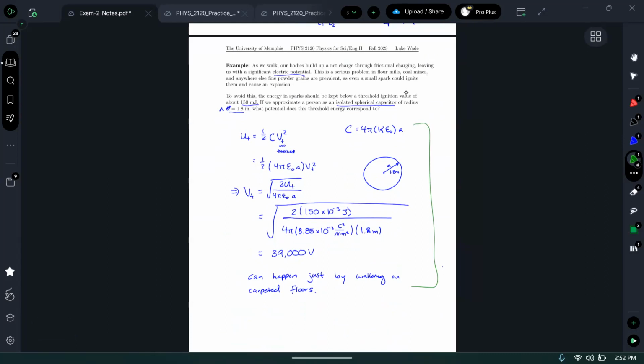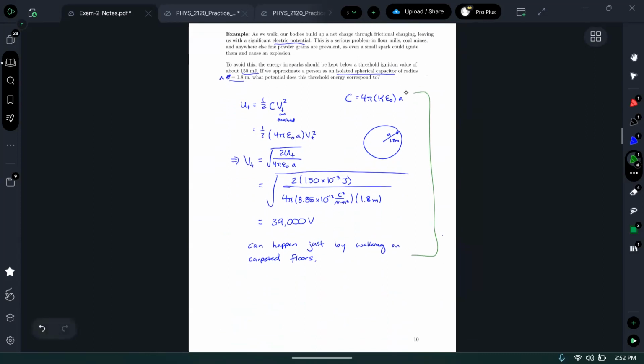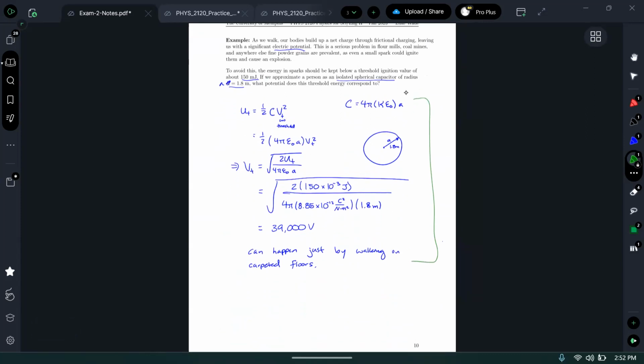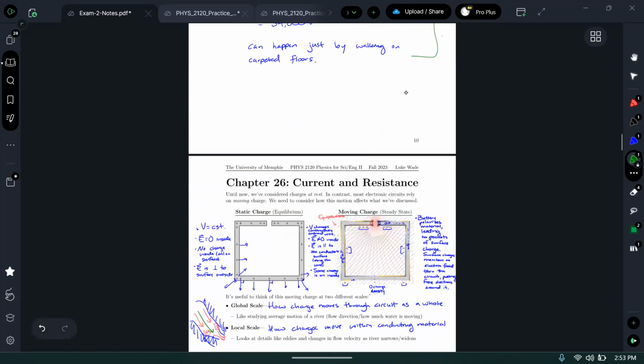To do that, you just have to look at that certain one, and if from previous steps you already know the voltage across it and the charge stored on it, that's pretty easy to do. You could use any one of those formulas. It's more for conceptual type questions that it helps to use one or the other to guide you, because the conceptual questions will say keep the battery attached, and so you fix the voltage, or you keep the capacitor isolated and fix the charge.